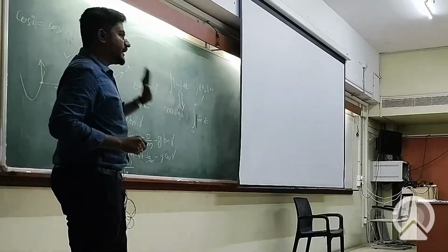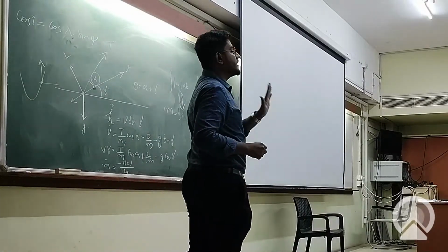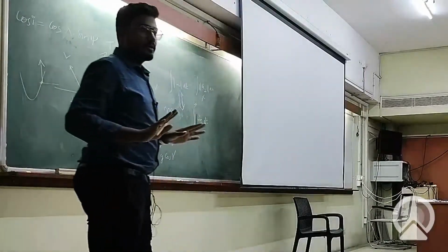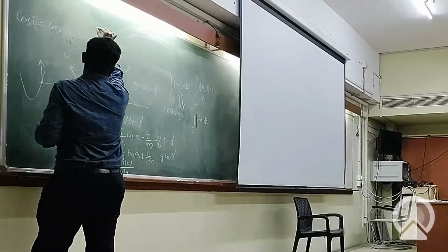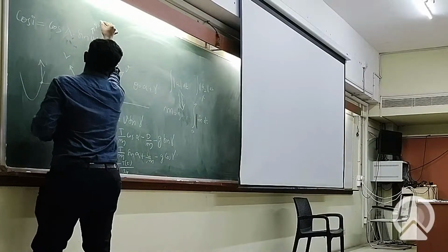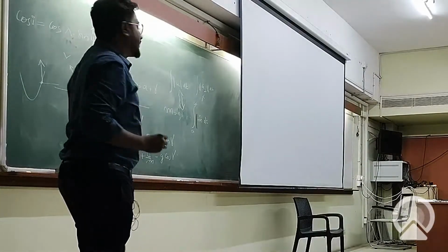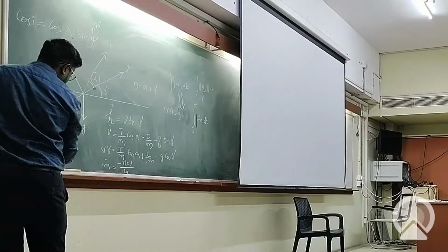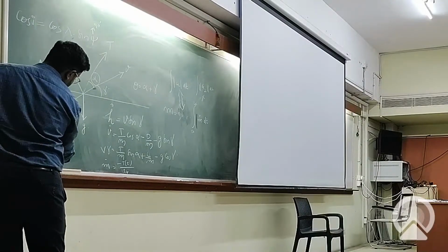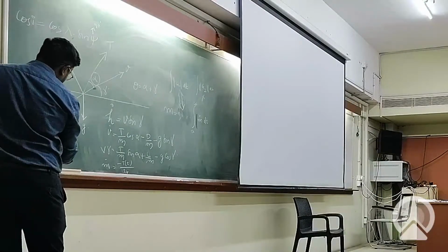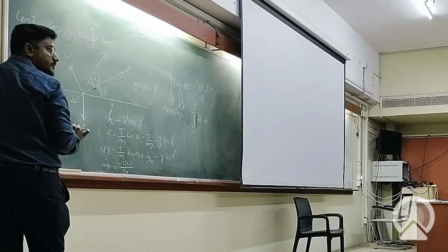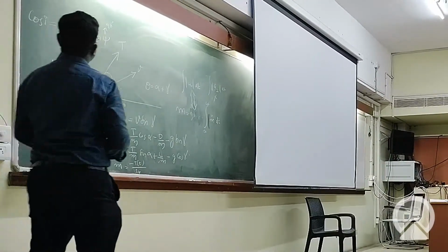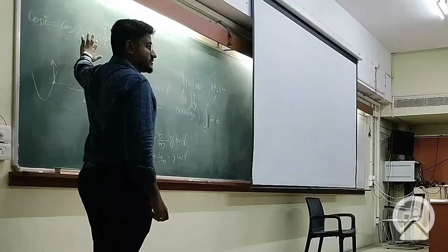In case of planar motion, you cannot achieve an inclination less than the latitude, provided you fly at 90 degrees azimuth. Because the Earth has to move around the equator, it's not possible to have it otherwise. So the minimum inclination that we can get is driven by where we launch from.